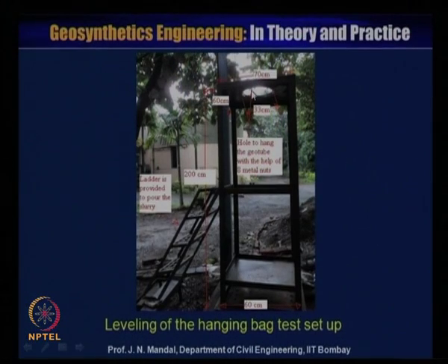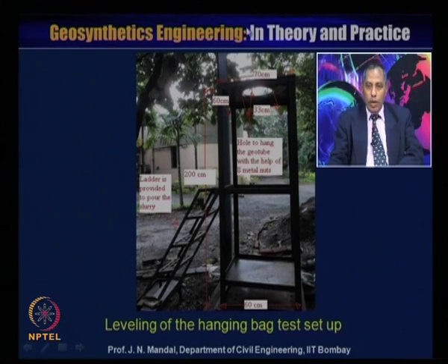So here you can see the leveling of the hanging bag. This is the setup, this is the frame, and this is about 70 centimeter, and the circle is 33 centimeter, and here this one is 60 centimeter, and from top to bottom is 200 centimeter, and this to here is 25 centimeter, and here you can see the pan, and here the holes to hang the geotextile tube with the help of 8 metal nuts here.